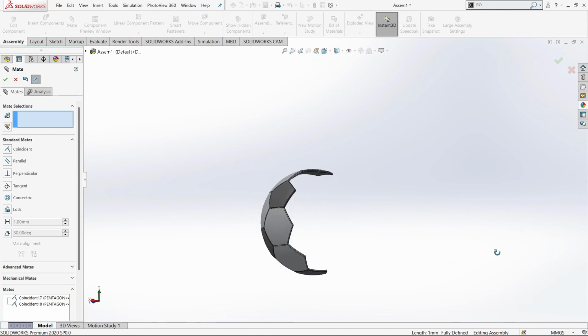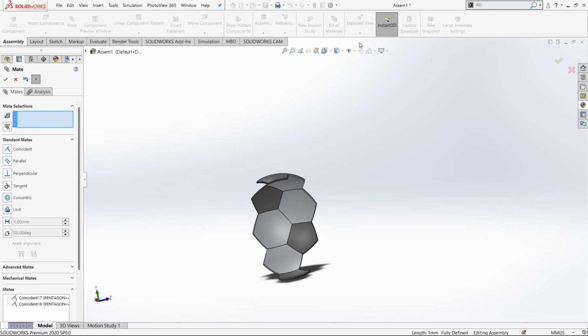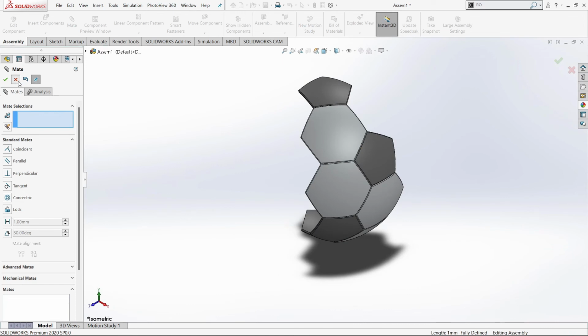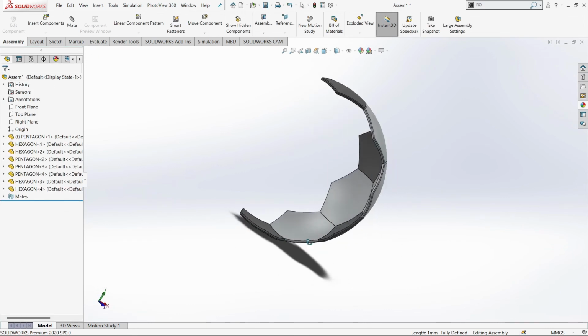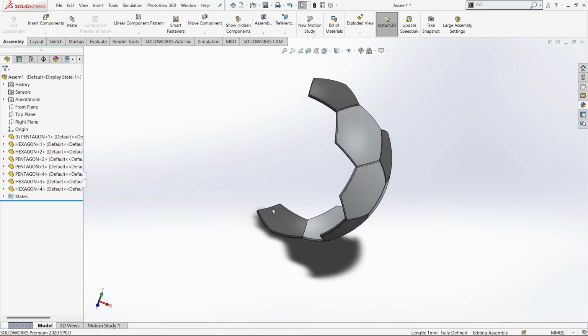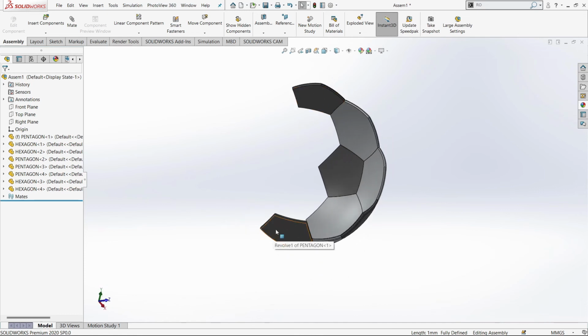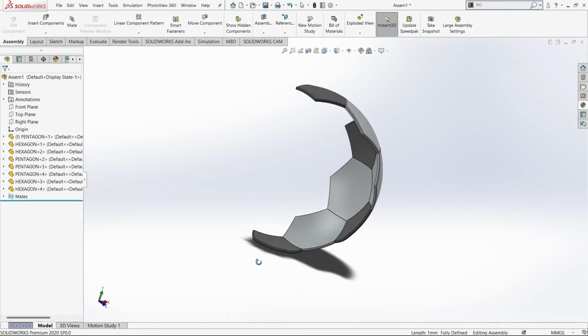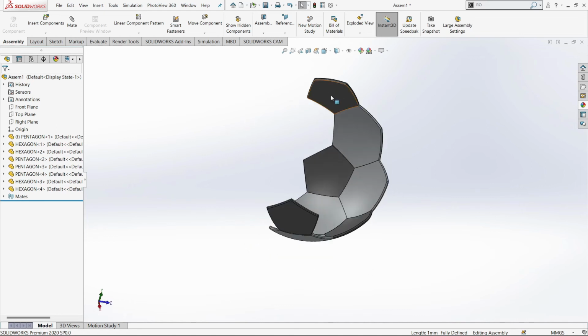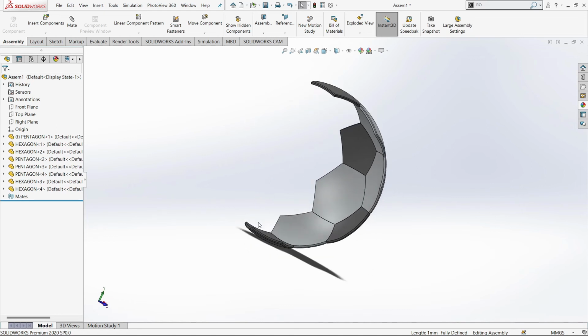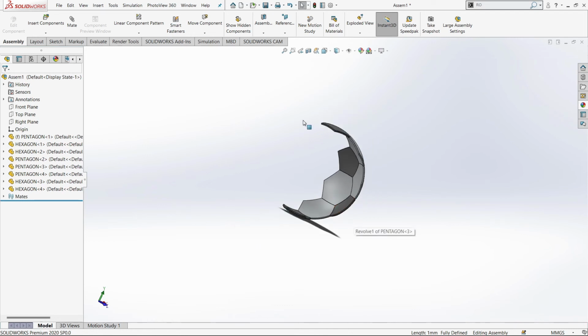So this will be my total assembly of this. But now almost my work is done, as you can see. So what we're gonna do is make a reference axis over here with the help of these two faces. With the help of 2 points, we're gonna draw an axis. First we have to make 2 points on the center of this face and the center of this face. After that, we're gonna make a reference axis against which I'm gonna revolve, or pattern, this total instances over there. What we're gonna do is now